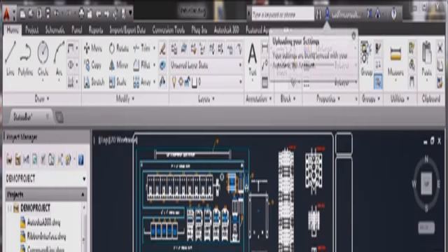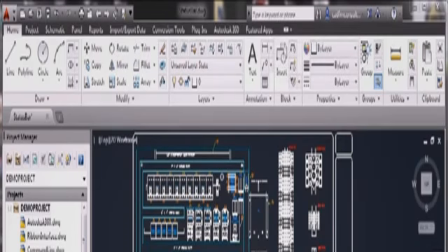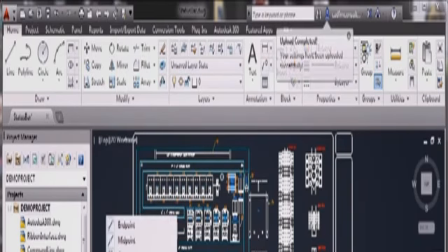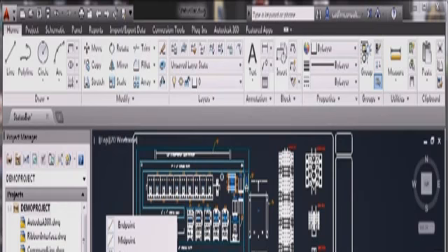So those settings for the drafting settings are great, but when you look at those icons, if you're a new user especially, you don't quite know what they mean. So if you move over any of the buttons, the icon buttons, and right-click, a shortcut menu appears. Now, I've right-clicked over the object snaps, so there's all my object snaps there. I can switch them on and off there as well. But if I just click on this Use Icon setting, it turns all of the icon buttons into buttons with letters on. Now, this is the old classic setting, and I actually prefer this both as an instructor and as a user because it tells me exactly what those buttons do.